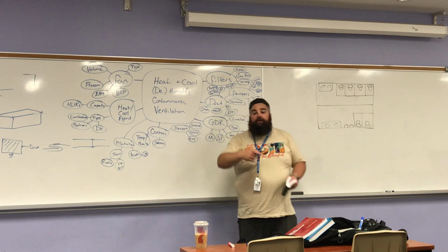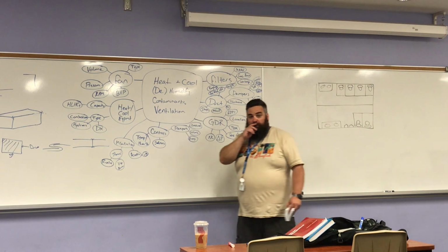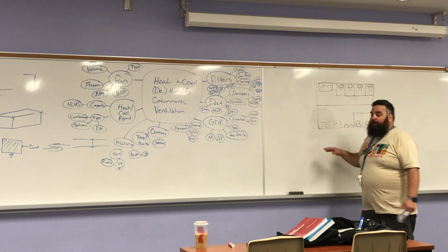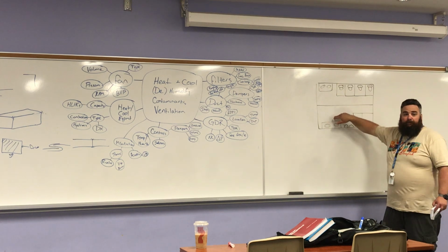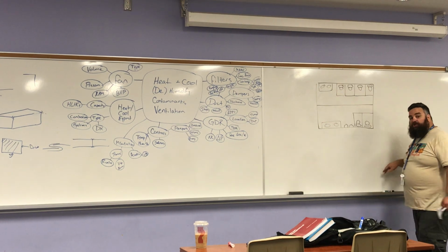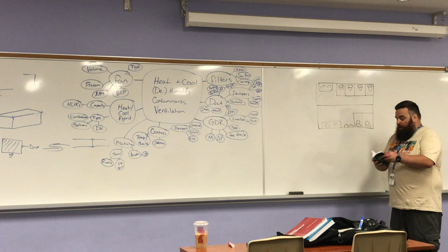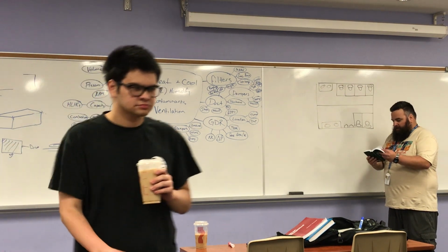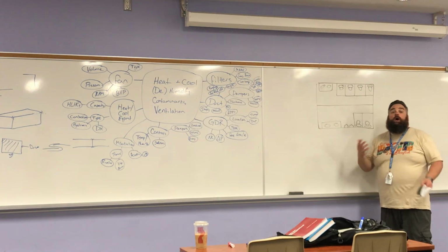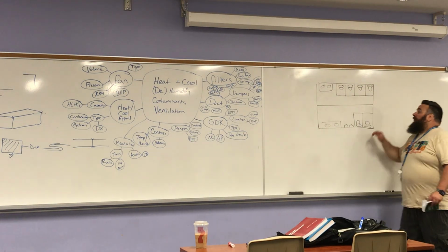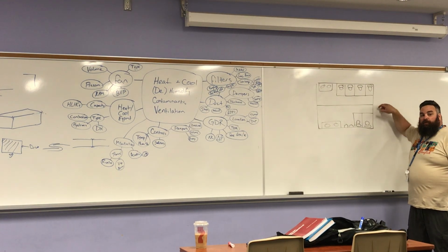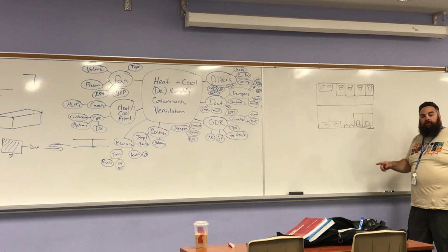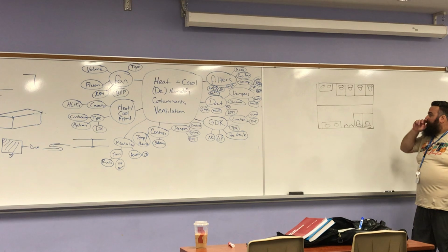So I need to bring in a certain amount of fresh air, right, for ventilation. Let's say, we're not going to do this in this example, but let's say I chose to do this with an HRV. The HRV is discharging class 2 air, but the ventilation air I need coming in is going to be, let's say, class 1 air. So I have to have 10 feet of clearance between them because I can't risk that contaminated air being drawn back into the space, okay?